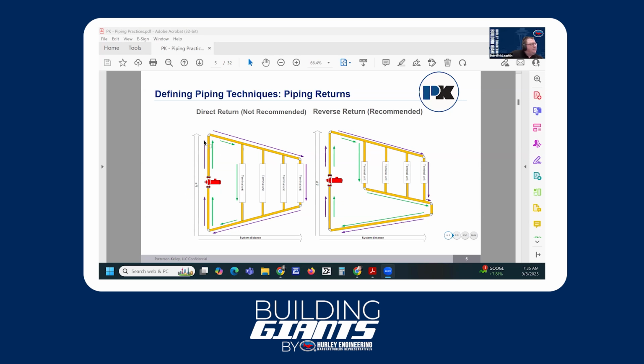So in this type of arrangement, we have different head loss through each different branch of our piping tree here. And if we don't account for balancing this with either valves or control valves or pumps or something along those lines, we're not going to have equal flow through each of our branches.